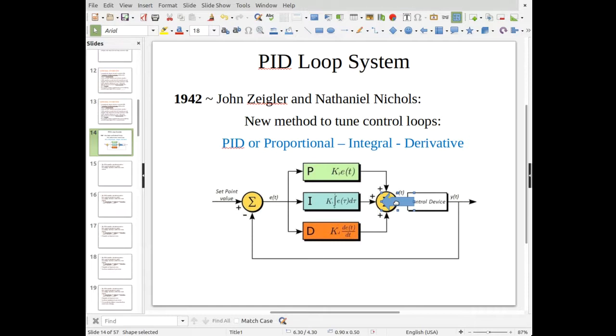If you're trying to push it to the set point, but you don't have enough drive in your control system to push it that hard, then you're never going to get there, so you're always going to have some steady state error. So when you build your system, you need to make sure that you can drive it to the set point, however much energy that takes. Otherwise, you're never going to make it to the set point, or you have to lower your set point, I guess.